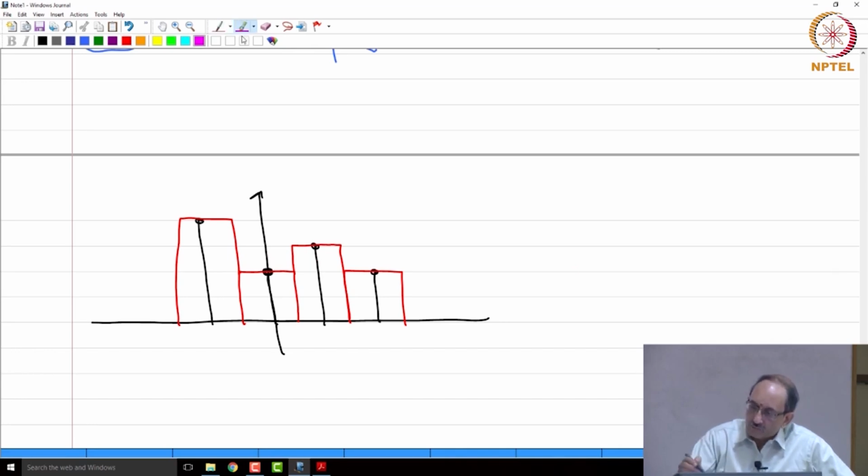So this sample comes in, you hold that value, next sample comes in, you immediately jump to that value. So the underlying reconstructed curve before further processing is needed is like this. So this is the waveform that is there, but this waveform has all kinds of discontinuities. So you need to pass this through a low pass filter, you will get a smoothed output, and that will be an approximation to the analog signal.